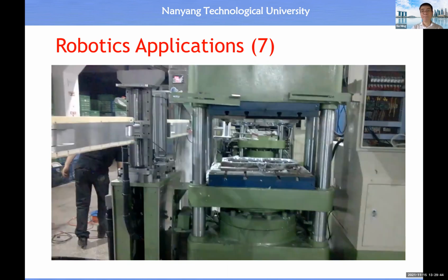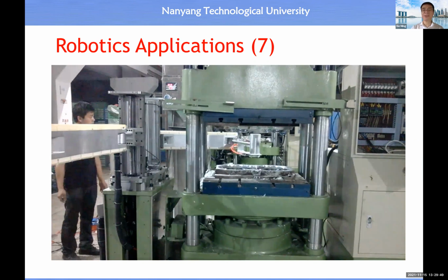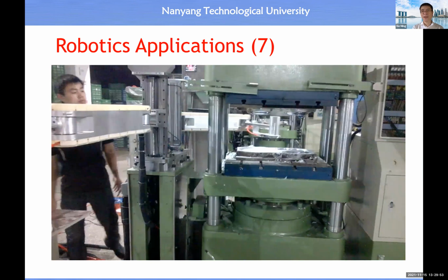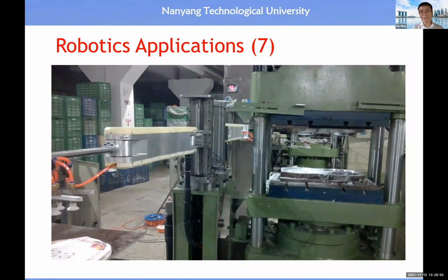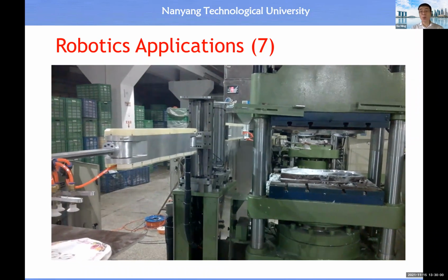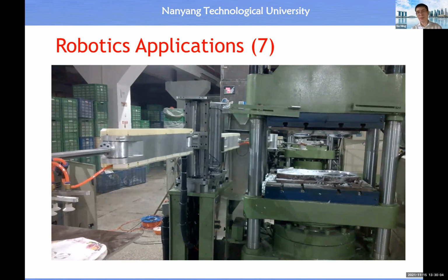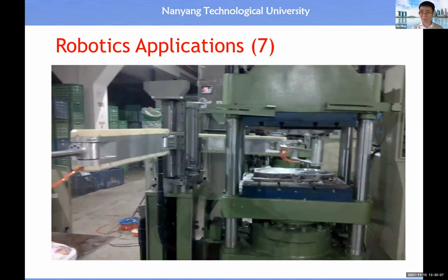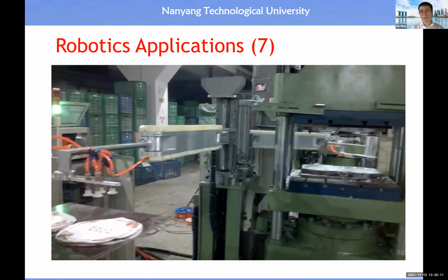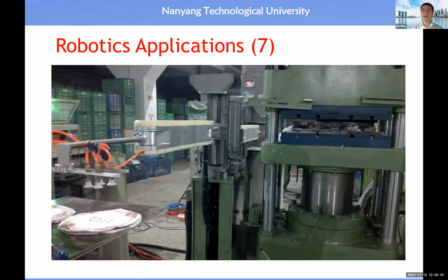So you see the input powder of a specific material. Then we close the die. Okay, in this case, we have 2 cavities inside the die. Therefore, we need to supply the powder to both of them. Now we close up the die. So you have an upper die and a lower die.